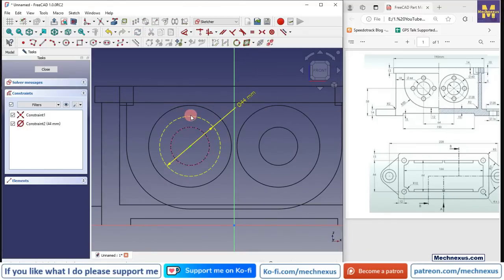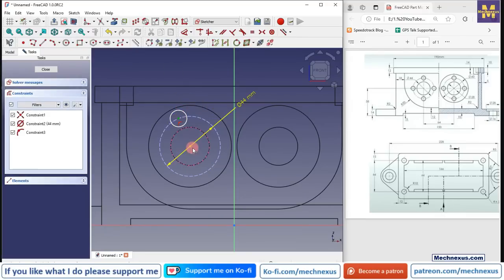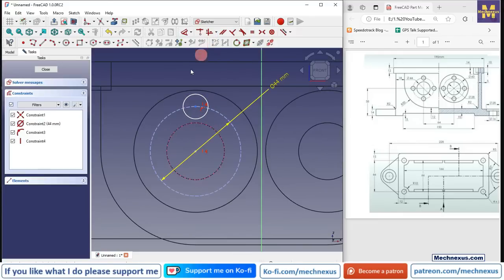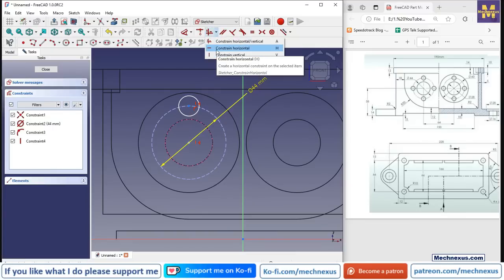Now we will create a circle and select this and add a vertical relation. So that is the beauty of FreeCAD 1.0. When you apply this constraint, it automatically detects whether it is a horizontal or vertical one.